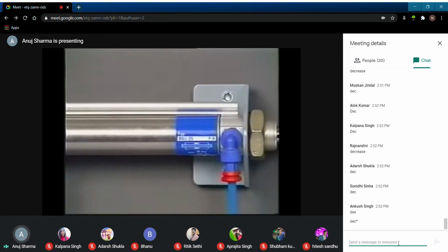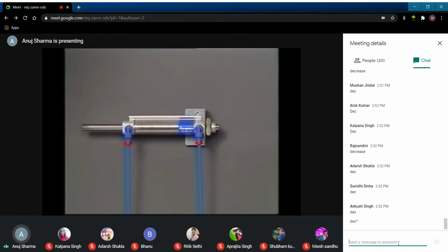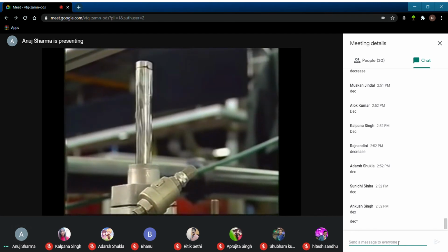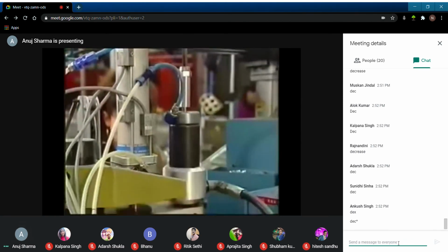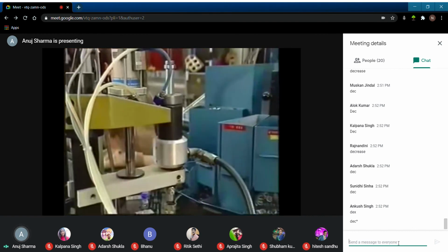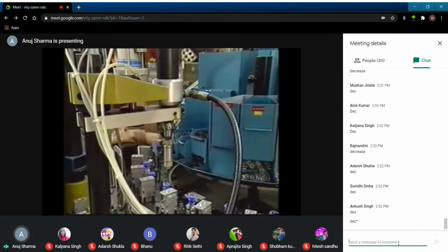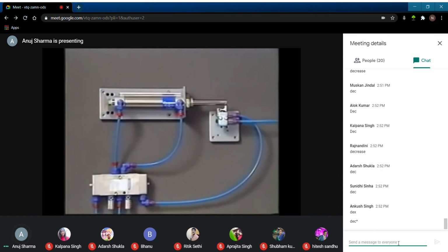Next, let's examine other types of cylinders. For example, this double-acting cylinder has a double-ended piston rod. This design provides more precise linear movement due to the two bearing surfaces. When heavy tools are not mounted along the axis of the cylinder, their weight applies forces to the side of the cylinder that can be compensated for by double-ended piston rods. Another advantage of double-ended piston rods is that the ends not used for the application can be used for other functions, such as end position sensing.